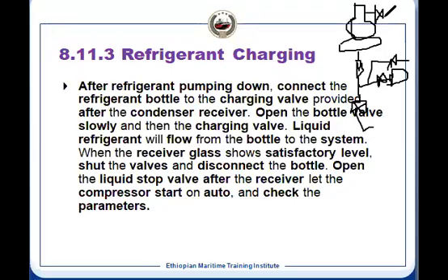And before that, there will be gas charging. And this is coming from your evaporator. Now, which one is better? So better we use the liquid charging. That is the reason modern ships many times will be saying that there is no charging point provided. Why is it better? Because if you charge a liquid, it means we are charging in the liquid line.